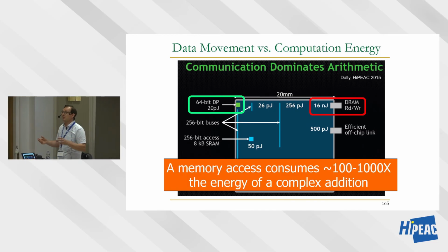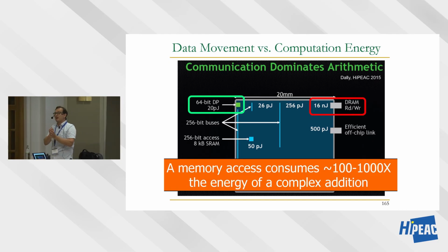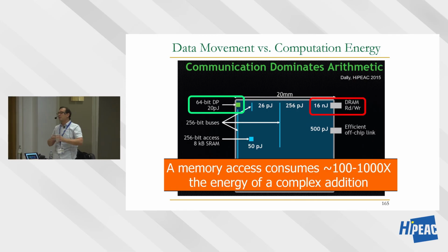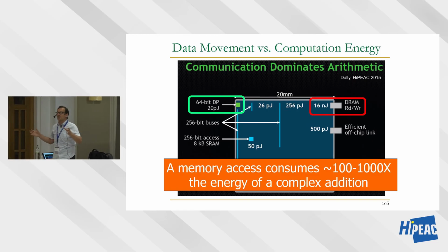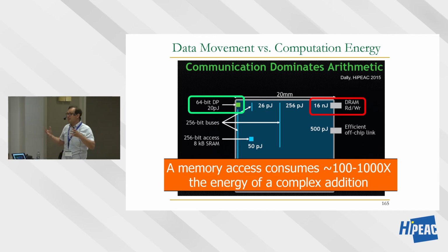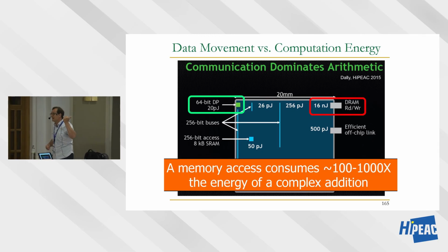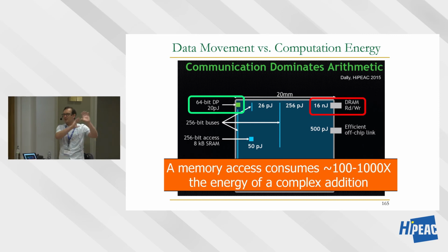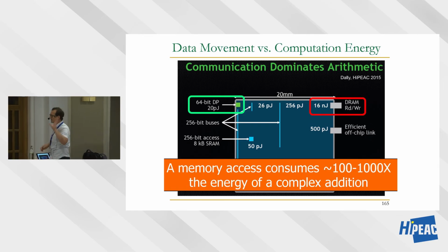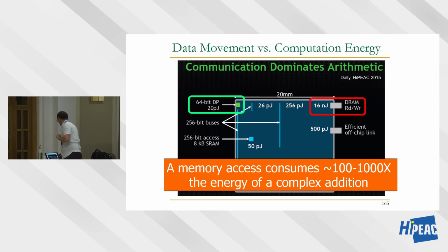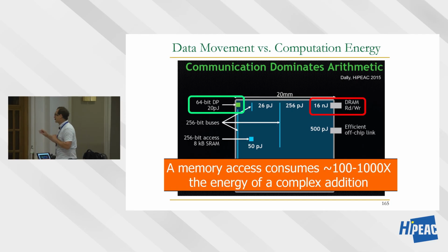Now the question is, does it really make sense to bring the data to the chip to do this very simple, energy-simple operation by consuming a lot of energy? Of course, it's a scientific, an optimization question. When does it make sense to do that? It does make sense under some conditions, but those conditions require the data to be reused many times by the operations that you're doing on the data. That many times you can calculate depending on your memory hierarchy, and it usually tends to be thousands of times, at least hundreds of times, depending on cost and memory hierarchy. And in many applications today, we don't have that amount of locality, like graph processing.